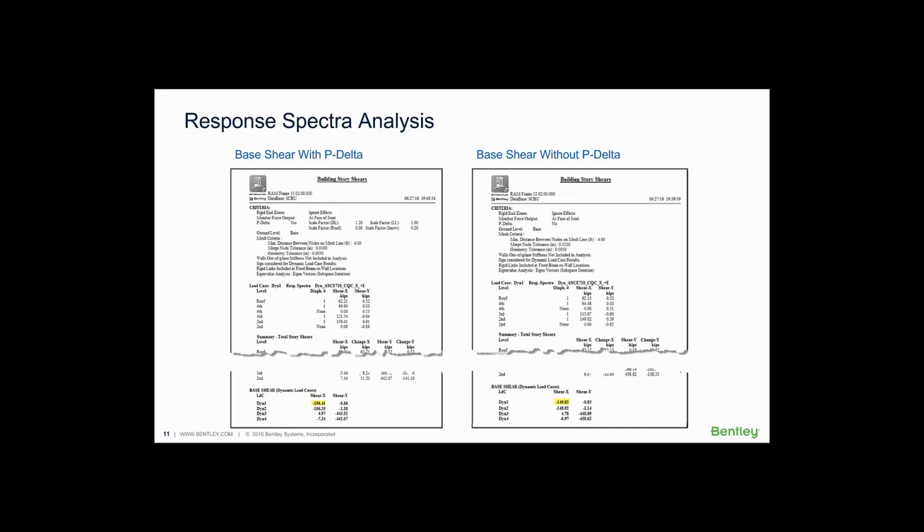That's a good question. That depends on what your software does. I think traditionally people have held the iterative P delta analysis in higher regard than the geometric stiffness method, but as my presentation shows, there is value to the geometric stiffness method.